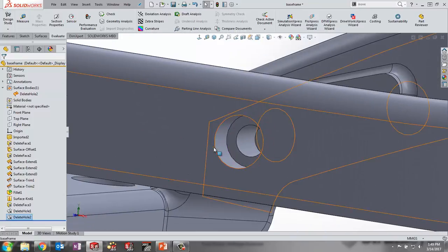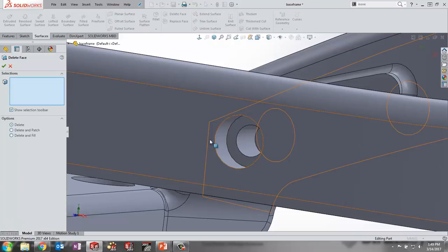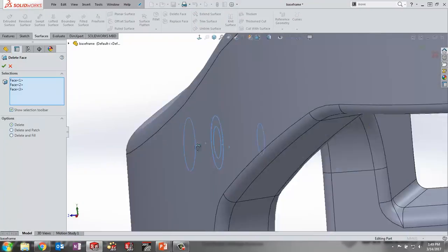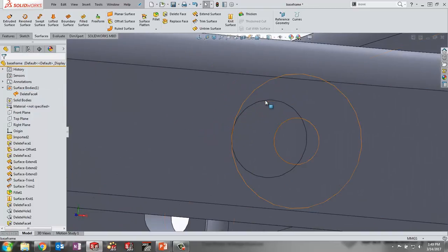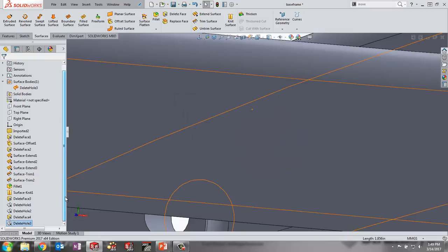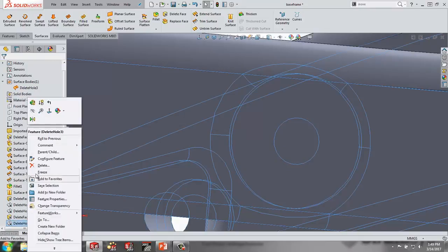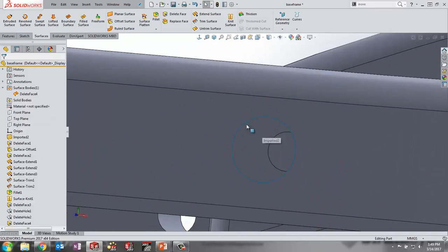Now, let's take a look over here. Let me do a delete face on this guy. And I'll just leave it at this for now. Say we try to do a delete hole. In this case, it's going to work, but say for some reason it didn't work. Let's just get rid of it. What we can do, if we wanted to fill this in but we don't want this face in here, is do a nice little fill.